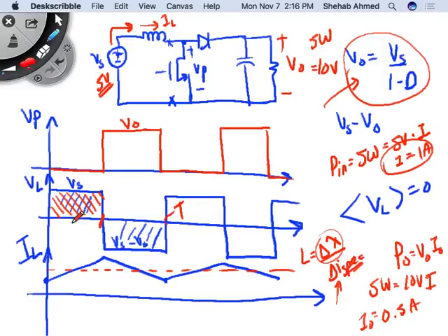I know that the period here is capital D times T. T will depend on your switch. T is your switching period, or 1 over your switching frequency. Right? So this area you can calculate. This is without any equations. No equations at all, just the waveform. By understanding waveforms, you can calculate inductance. Next. So now I have inductance calculated, I have diode calculated, I have switch calculated.